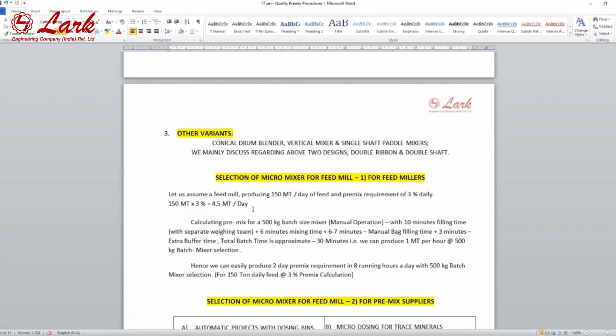So by reducing the RPM with the help of the VFD, we can reduce the tip speed. Even at 1200 or 1400 RPM, the hammer mill is not able to prevent 100% of the dust, but you can reduce the dust from 25-28% to 5, 7, 10, 12% with the help of the VFD.